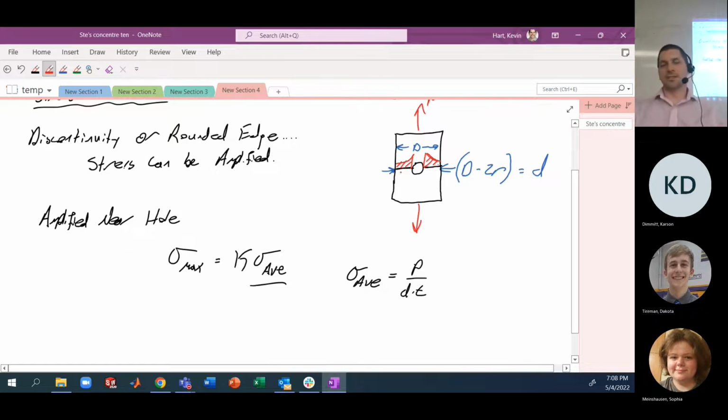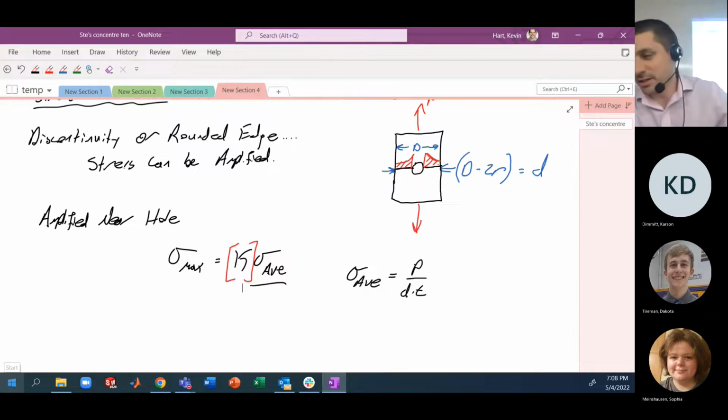Okay, this is one specific case with increased stress from tension, but we could also have similar ideas from torsion and from bending, and we saw examples of all of those in homeworks and practice problems. The actual stress concentration factor, this K value, comes from geometry only. So it's independent of material, and it strictly comes from geometry.